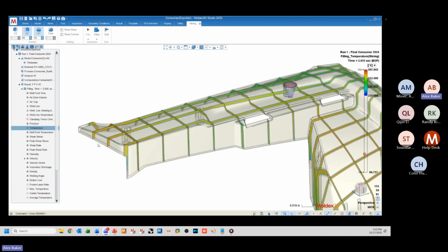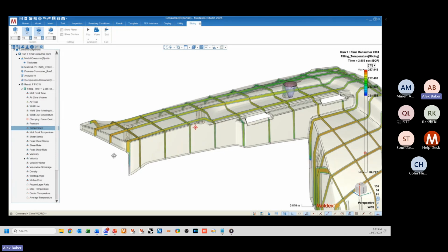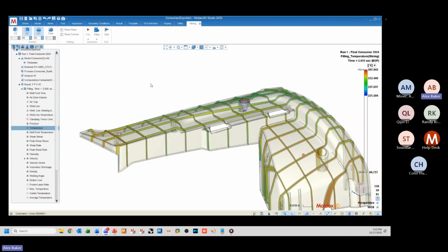This here is what we call the shear effect. The energy released into the mold is what we call the cooling effect. And so which of these effects is dominant will dictate which area of our part is the hottest. You can see that in this case, the end of fill is the hottest, so therefore the shear effect dominated. If the temperature decreased over the length of fill, which admittedly is the more common scenario, then we could say that this was a cooling dominated flow.